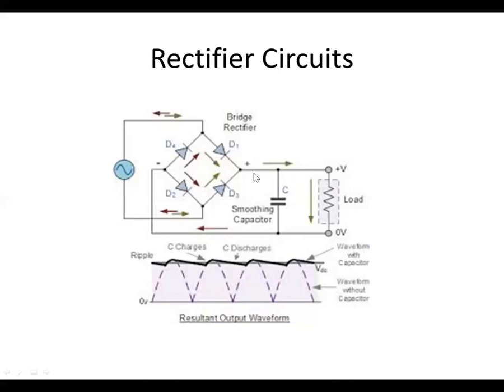A safety note with this type of power supply: these capacitors can remain charged even when you turn this off. So generally there's a discharge resistor in the circuit that has a much longer time constant, so over several seconds or maybe even a minute, it'll discharge that capacitor. If you need to open up a power supply, shut it off, disconnect it, and wait a while. You might even want to check the voltage on that big electrolytic capacitor to make sure it's discharged, or you can get bit pretty well.